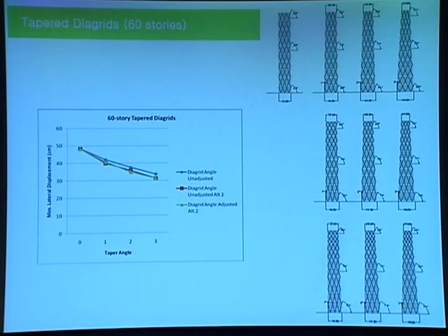So there are a couple of other options in this case. The second group makes the diagrid structures by adjusting the module height, giving a configuration close to a uniform angle. And the bottom case adjusts the diagrid module height further, so that the shallow angle goes at the top and the steep angle at the bottom, which corresponds more to the basic structural phenomenon occurring in tall buildings.